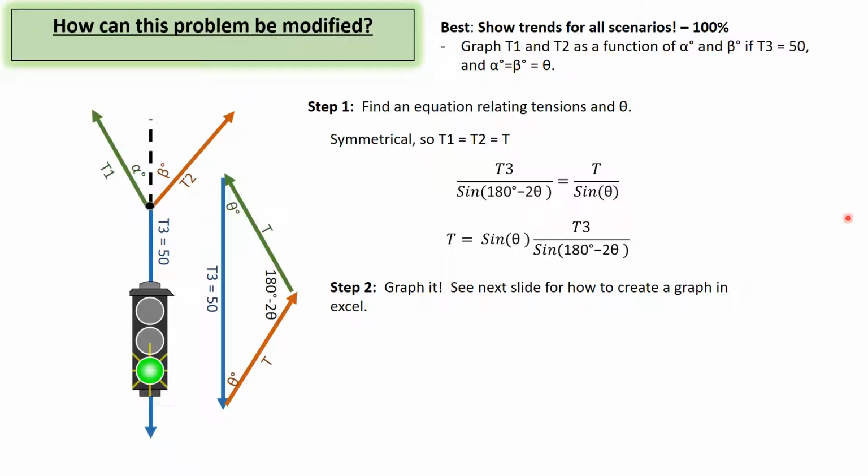So let's just set these up. And it's the same equations that we've used before. All we're doing is, instead of putting a number in for these tensions, we're just going to leave this as a variable. And I'm going to rearrange this equation to get something where we have the tension in those cables, and I've simplified it by making these two angles equal to one another. So alpha and beta are here equal, the tensions are equal, and this tension ends up being just sine times T3.